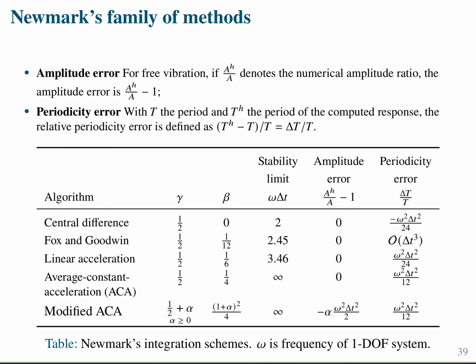Unless contact is very simple and you can use some very simplified node-to-node contact strategies, yeah, you may get a nice solution in the contact. Try to use impact? Forget about it. It's crazy. You have energy conservation? I'm not so sure. And then, let's say you have sliding and now you don't have node-to-node anymore, and you have node-to-element, what is called node-to-segment or segment-to-segment contact, and try to get proper transfer of tractions or a numerical scheme that does not produce oscillations of the contact traction. It's a nasty problem. Nasty.